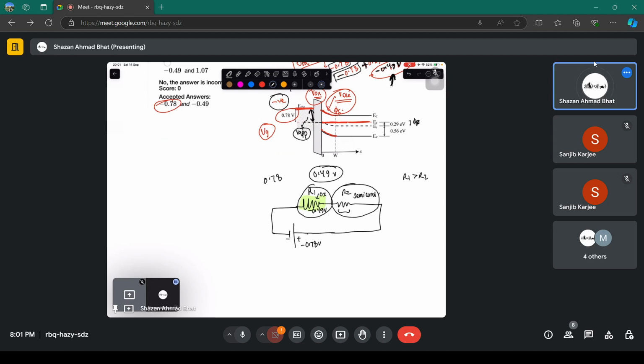When you move on in this course, you are going to get more terms. Whatever gate voltage you apply drops across the oxide, drops across the semiconductor surface, and also drops in maintaining something called flat band. This comes because there is a difference in the work functions of the metal and the semiconductor, and there are fixed charges present inside the oxide. Okay, so Q is C times V, and you can get V as Q times 1 over C ox.